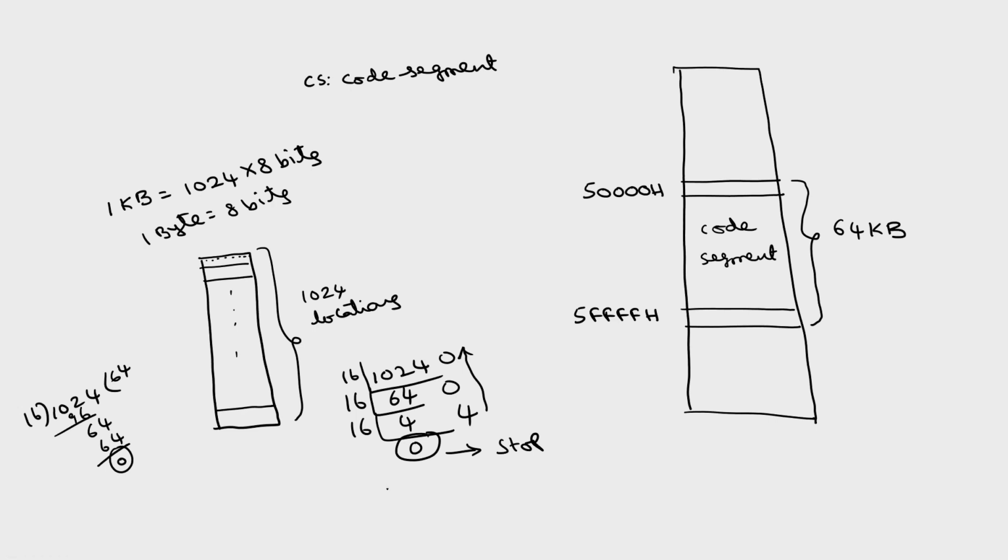So if I want to start with 0000H, because this is 400H, one less than this is called 3FFH. For this 3FFFH, if I add 1, F is the maximum number, 15. In the case of decimal, 9 is the maximum number. If I add 1, it becomes 10. So F plus 1 becomes 10. Okay, if you start with 0, you have to take the value which is 1 less than this 400H. So 0000H to 03FFH is called 1 kilobyte.